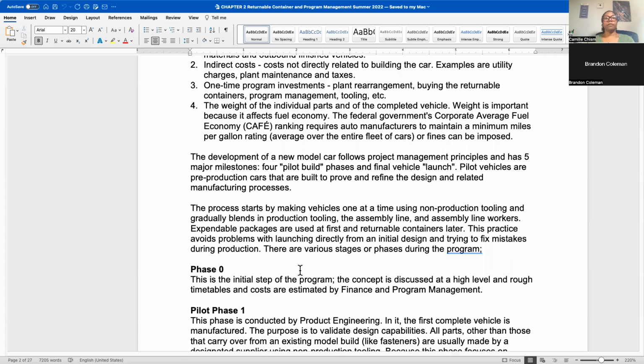At this point, regarding packaging, many times what should happen is that the packaging should already be planned out and expected. What many times happens is they just ship it in a corrugated box and say, we'll worry about that later. But as a packaging engineer, I'm going to stress to you that at this point, you want to be involved in these build events as often as possible, because that is one of your chances to see, is the packaging working?